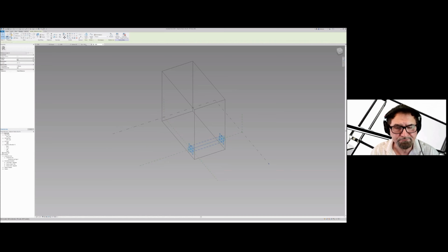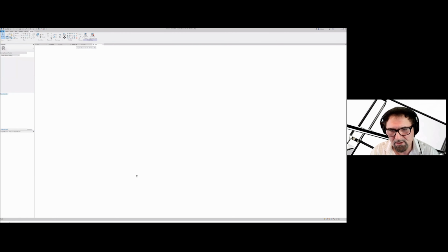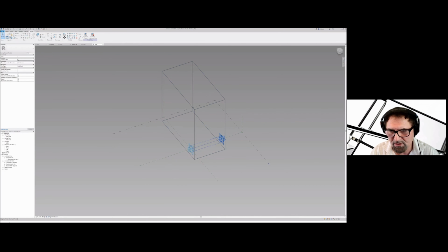Prior to that, I was designing the profile, and the profile is also fully constrained to this reference point. Later on, we make a couple of insertions of that reference point onto the host line, and we control that the profile will be swept from the exact beginning to the exact end of that reference line.